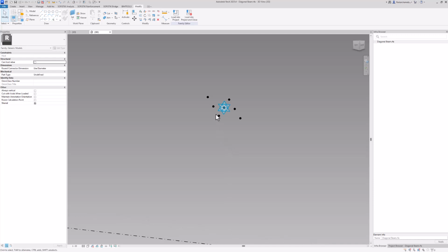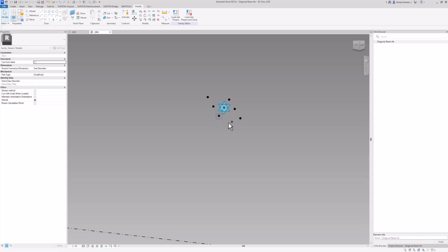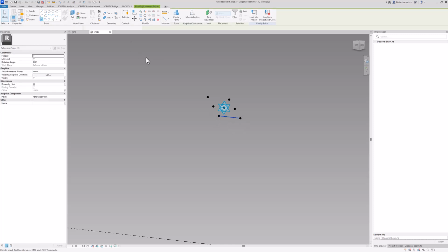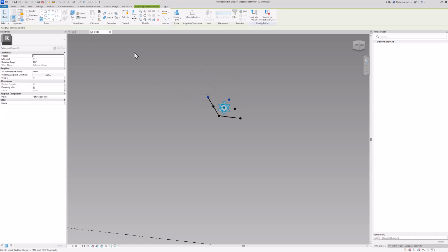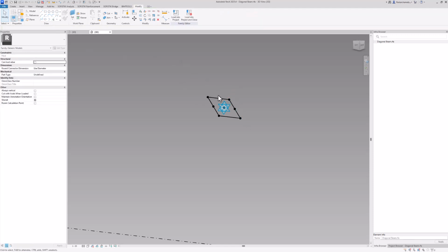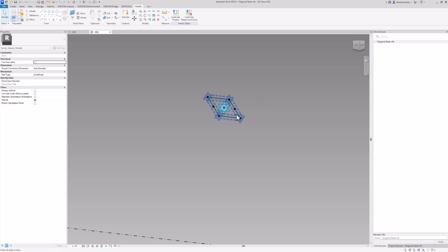All right, what's the goal we want to achieve? I simply select the corners, 2 of them, create a line, select another 2, create a line, and now everything we did starts to make sense, in which we now created a parametric rectangle. You can select this rectangle. This is supposed to be a reference line once more, which is not a reference in your project, meaning that it will not highlight once you hover with your mouse over it.